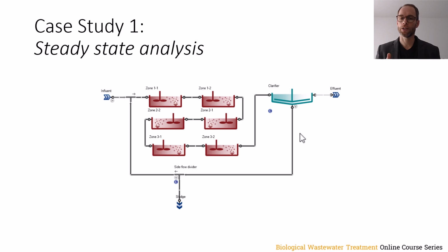After iterating a few times around modifications to the influent wastewater fractions, so the fractions of the COD, and adjusting the SRT to better reflect what they thought they were operating their plant at, we were able to get within 10% of the reported mixed liquor suspended solids concentration. So the model that we used was within 10% prediction of the mixed liquor suspended solids concentration, and maybe within 11% of the reported sludge production in the waste activated sludge stream.